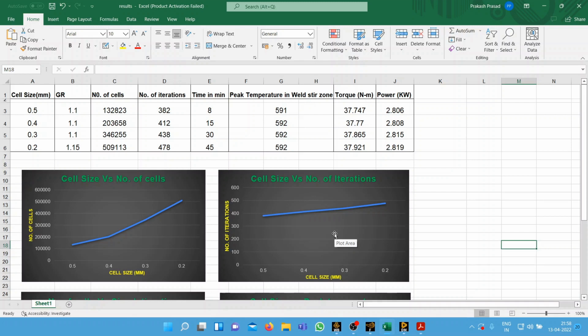So here we can go with the element size of 0.5 mm, because the computational time drastically decreases. In order to get a similar result, it is better to select the control volume size, that is, meshing of the control volume with the required number of elements and element size. That was the interesting part I came to through this analysis.